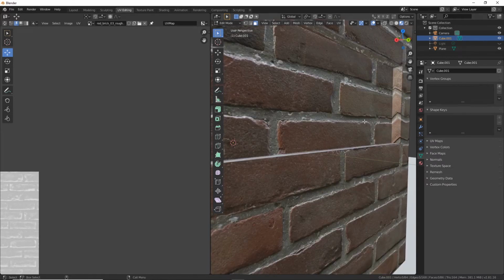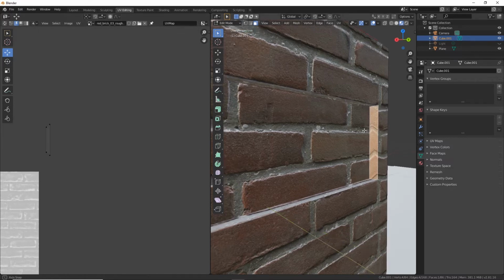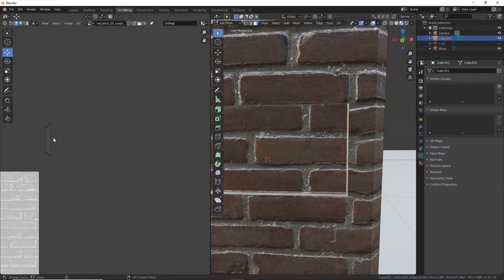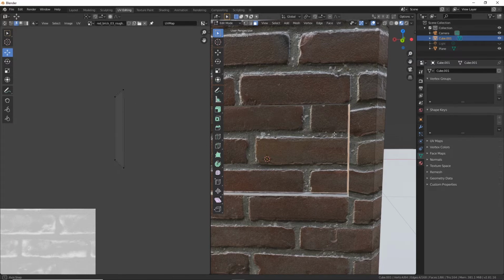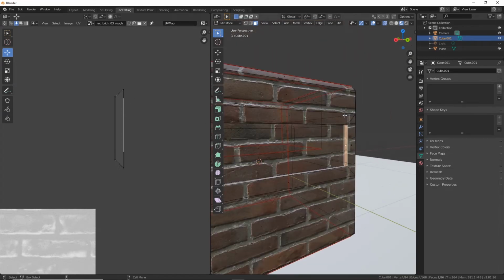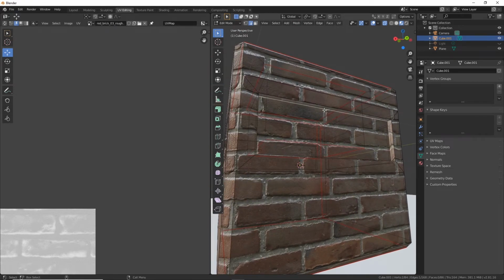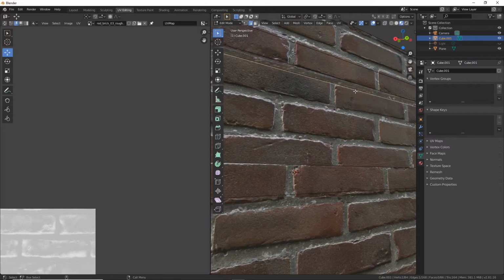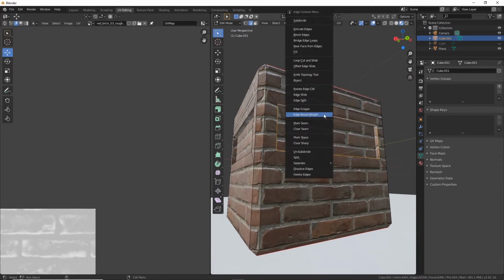So still not great on this face. The reason being that this is a straight end bevel and it shows as a kind of a true bevel where this is getting flattened because of the way the bevel is connected. So if we go and just disconnect, actually we can just do by line here. Double click, can select across, can select that way and just mark seam.